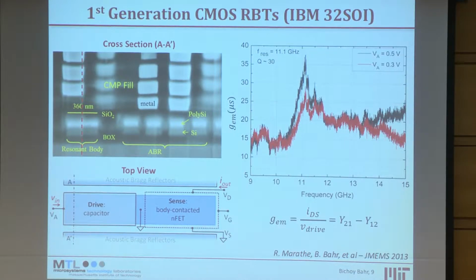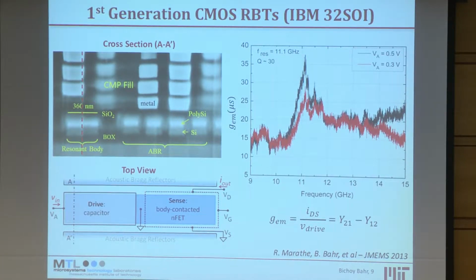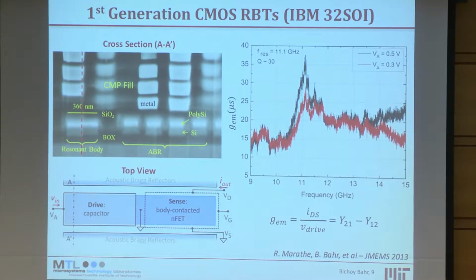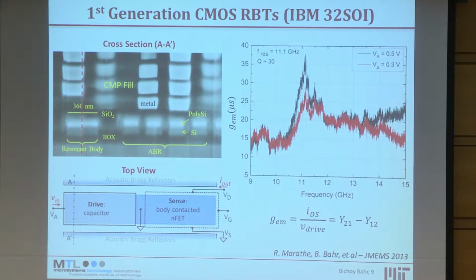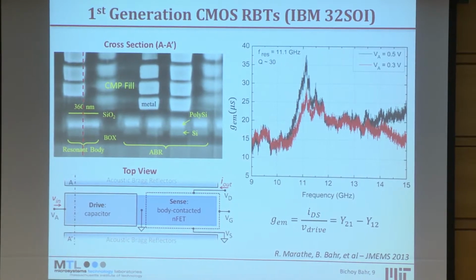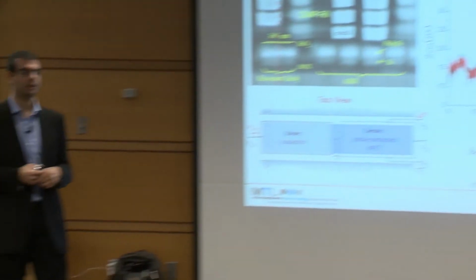I guess most of us are familiar with Bragg reflectors from optics, when you basically have transparent dielectric layers, and when you stack them up with the correct thickness, that's exactly lambda by 4, you start getting strong reflections. So they start acting like a mirror. And it turns out we can do the same thing in acoustics, and people have demonstrated the same idea of acoustic Bragg reflectors back in the 1960s and also in the early 90s to do solidly mounted resonators.